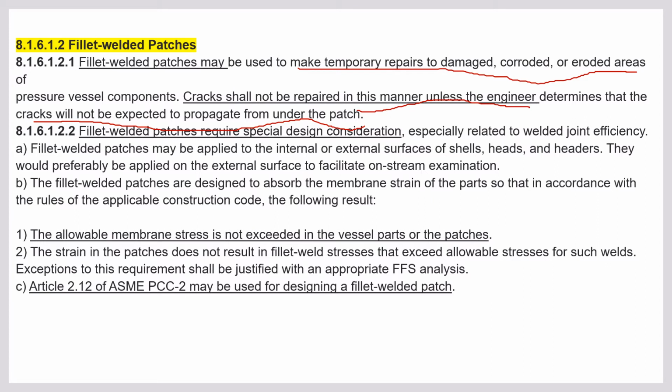Okay. So fillet weld patch requires special design requirement, especially related to weld joint efficiency. Weld joint efficiency is an important term. Actually, for this chapter, repair, alteration and re-rating, the most important is impact testing. Where impact testing is required and where impact testing is not required. Because based on impact testing, the repair, alteration and re-rating change a lot. We will read about impact testing after a few slides.